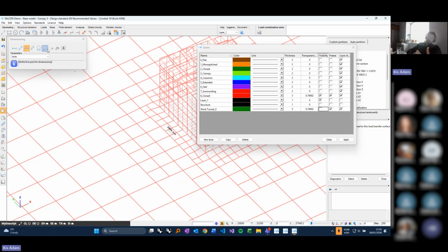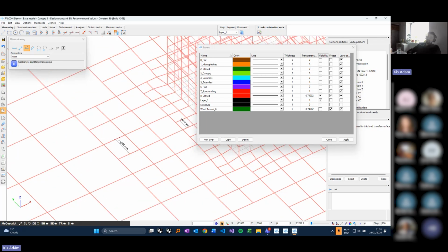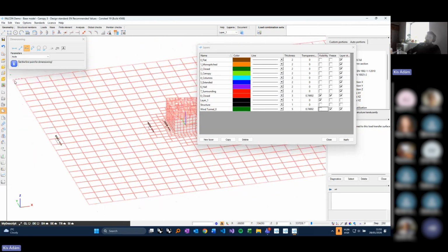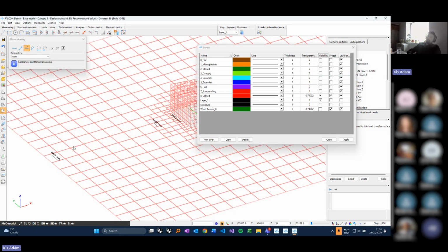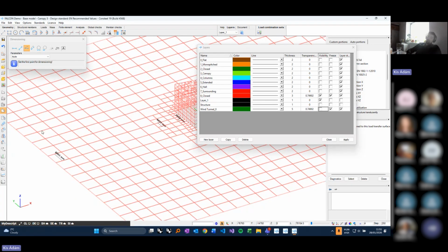By choosing the default value of 2 for the refinement factor, first we have a 4 meter, and ultimately an 8 meter mesh size close to the inlet of the finite domain, which means that we doubled our initial value 2 times. So 2 meters doubled 2 times, 2 to the power of 2, ends up with 8 meters.